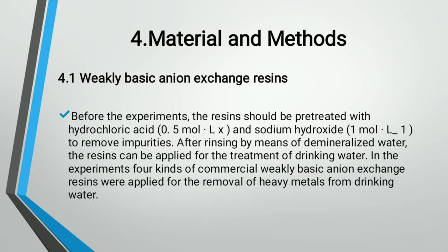The next topic is materials and methods. Weakly basic anion exchange resins. Before the experiments, the resin should be pretreated with hydrochloric acid and sodium hydroxide to remove impurities. After rinsing with demineralized water, the resins can be applied for the treatment of drinking water.